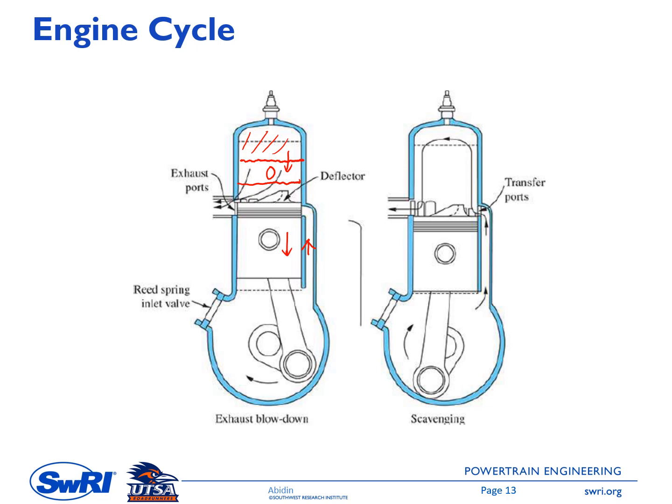So at some point the piston is at this location and the exhaust port opens first. Then because the chamber pressure is much higher than the pressure of this exhaust manifold, let's say this is 0, this is number 1, the exhaust gas will exit the chamber going into the exhaust port and finally leaving the engine.